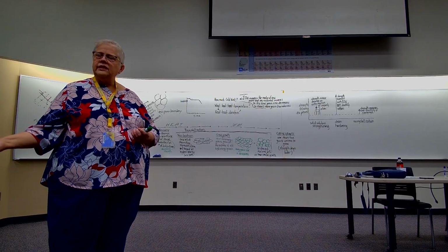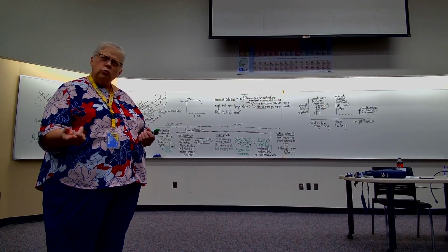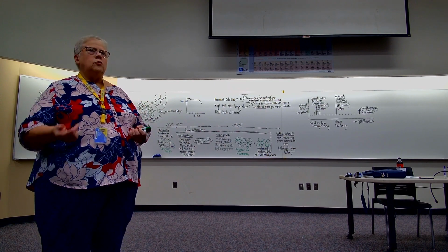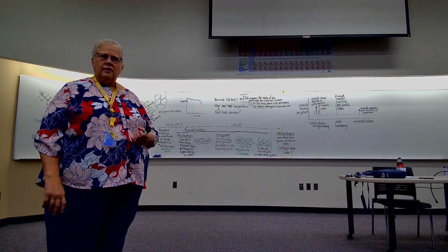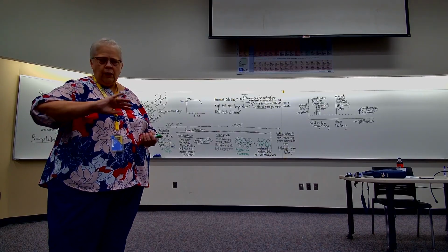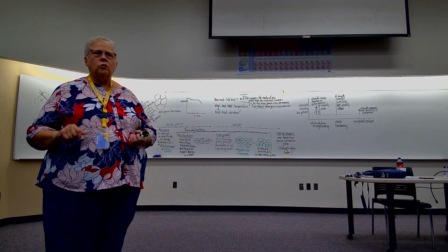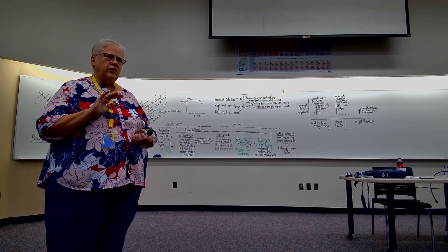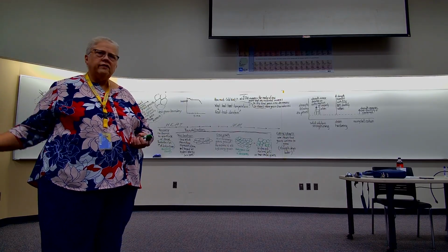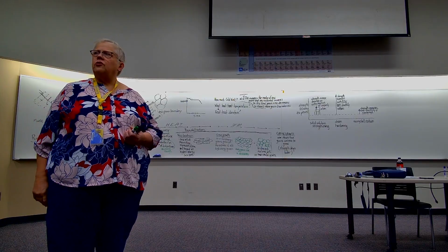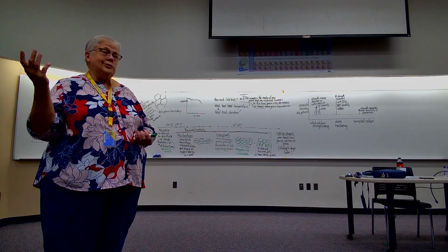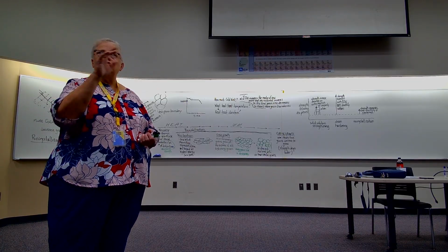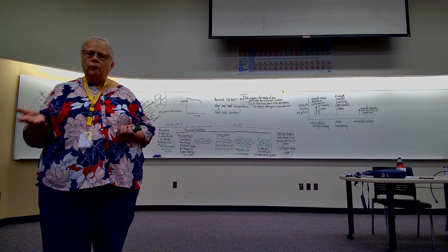Room temperature steel has two phases. One is mostly iron, one is iron with carbon. If we took a piece of steel and polished it and added some kind of corrosive agent so that it just starts to corrode on the surface, and we then get rid of that and look at it under the microscope, that corrosive material, called an etchant, will have etched those two different phases differently, and we'll be able to see them.